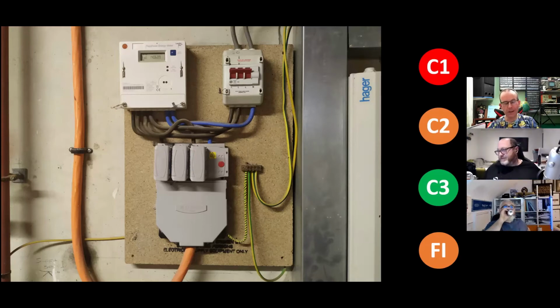This might look like a 3-phase supply, and it is a 3-phase cutout there on the cable, which goes back to another thing which isn't in this picture. But notice on the 3-phase meter there are only 2 of the phases connected. The middle one doesn't have any wiring attached. So we've got 2 phases coming out, going into that meter. Then going into the isolator, there are only the 2 left phases connected, and the neutral, obviously. And then on the top of it, despite it being a 3-phase supply, we're only actually connecting a single phase to the distribution board, which is on the right of the picture.